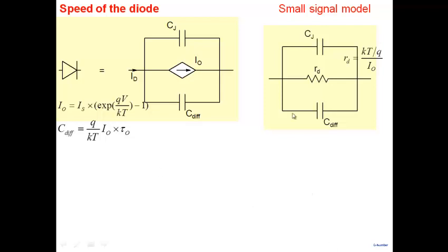That this current should be much, much smaller than this. So what will be the threshold point? Impedance? Much larger. Impedance of the same thing, impedance of the capacitor in terms of sinusoidal steady state, should be much larger than RD. Now, up to what point can you say your diode is working okay? When the impedance here becomes comparable with this, you can say you can't use it beyond that.